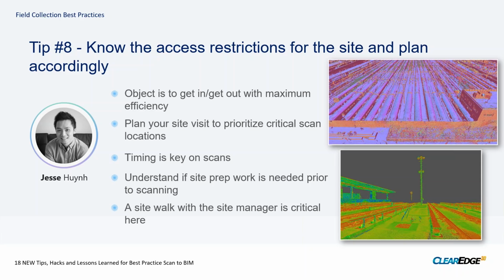Also understanding if anything needs to be prepped on site before you actually go on the site the day of the scan. If there's a lot of items on the site that may be in the way, if certain surfaces need to be covered up because they're highly reflective, or there's just way too much sunlight going on or not enough light, it's really understanding what you need to get yourself an optimal scan.